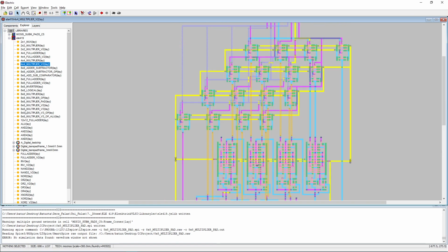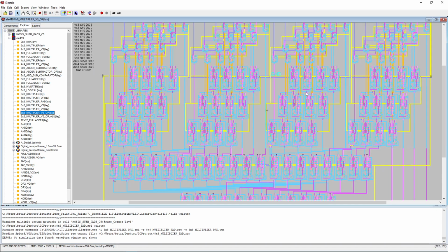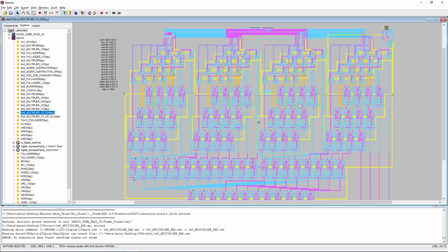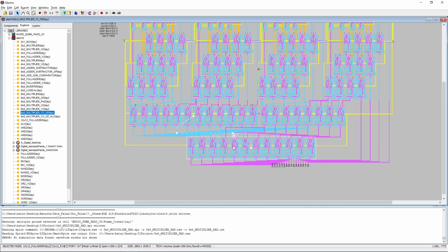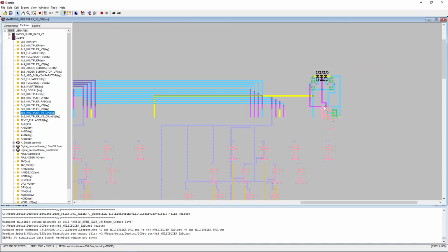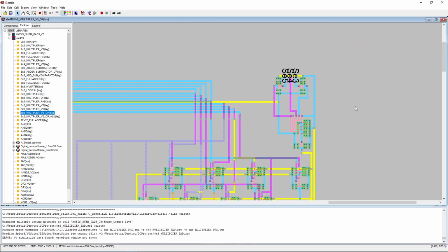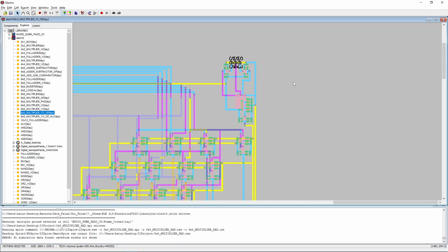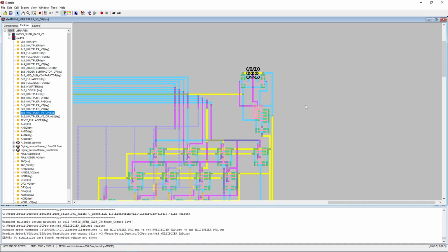I will talk about the 8x8 multiplier, but as you can see, there are a lot of versions. I will talk about two of those specifically. Now, this is my main multiplier. There are four 4x4 multipliers, two 12x12 full adders, and one 8x8 full adder. And there is a selection part here. This selection part helps us to design a specific opcode for the multiplier to respond to.